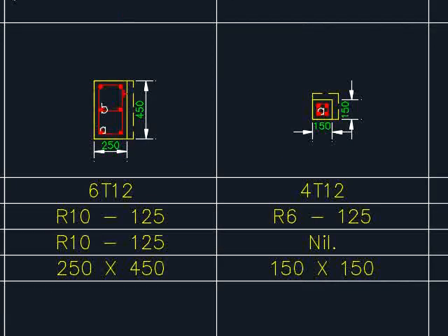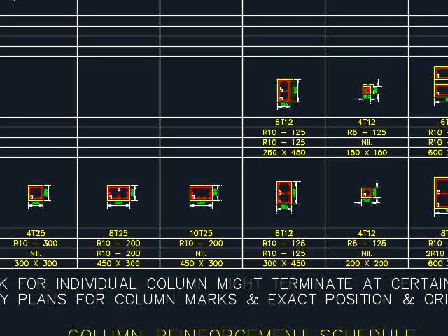In fact, you can have different positions of the columns put in different classes in the column schedule, but this will increase the number of types of column in the column schedule. Normally, I would prefer the technical drawing to be as simple as possible, limit the number of types of columns, and regarding the positioning of the columns, we will ask the contractors to observe themselves. Make sure it is made known to the contractors.